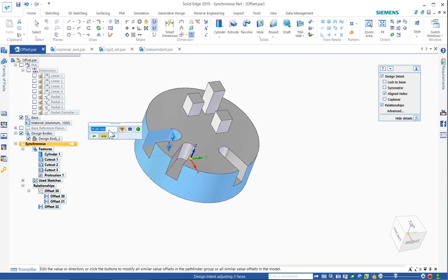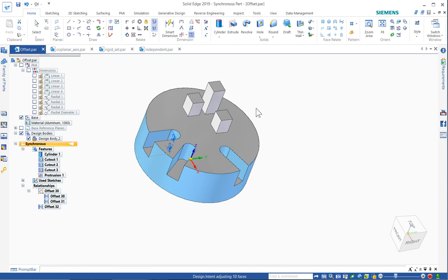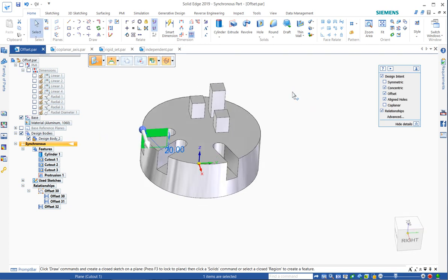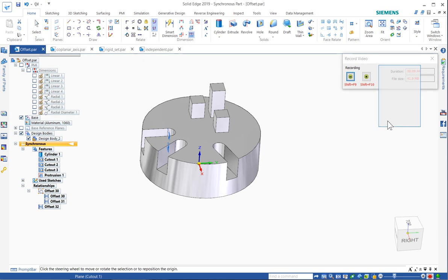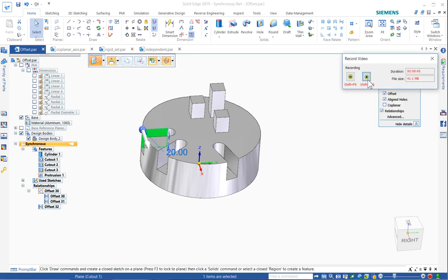So now I've kind of done 2, and I'm going to hit the select tool, so I'm completely out of that, and start again fresh, just so I can demonstrate something to you. And this slot now is actually the same width, but I'm just going to run the command again independently. And now you'll notice here something a little unusual in the relationships group where your relates show up. These two are grouped, and this one is separate because I ran the command again separately.